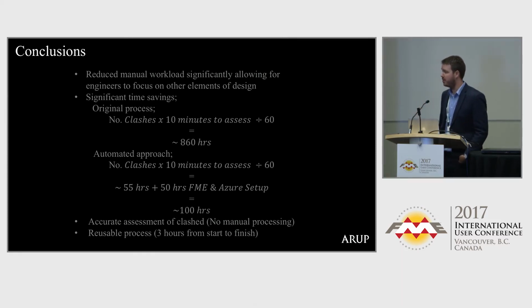So, conclusions from this process so far. I think probably the biggest one that we've had a lot of appreciation for is that the process previously was around about 860 hours to go through and process. You do your clip, and I'd go home for the day, and the utilities would sit there fumbling along for quite a few days, weeks, sometimes months. But our process automated that down. So if you take out the 100 hours it took me to set up that analysis process, you're still saving about 700 hours just on the clash detection analysis side of it.